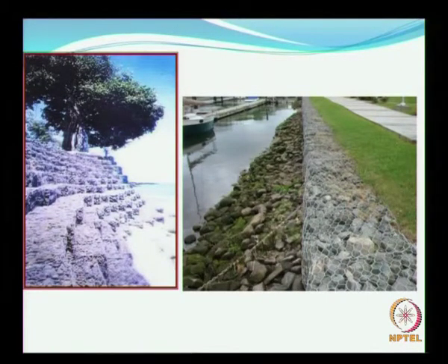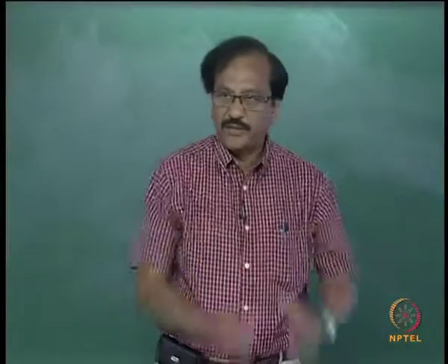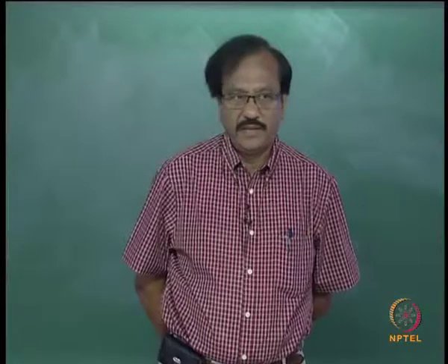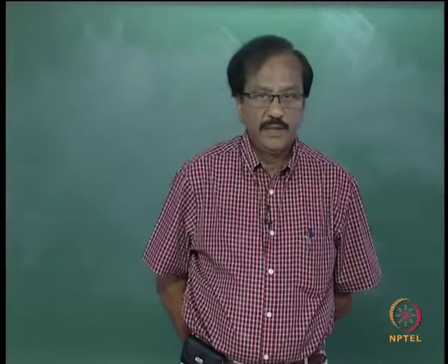So, this shows the use of gabions as we have seen earlier. This is somewhere in South Africa, near Cape Town, where you see the gabions and the stepped wall. As I told you earlier, the stepped wall can be impermeable or it can be formed with gabions. With gabions it can be more effective because some amount of energy is dissipated because of the porous medium which we are having there. Is that clear?